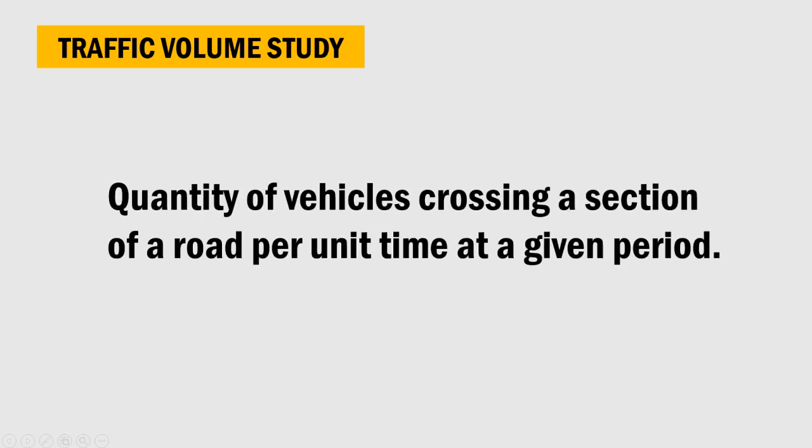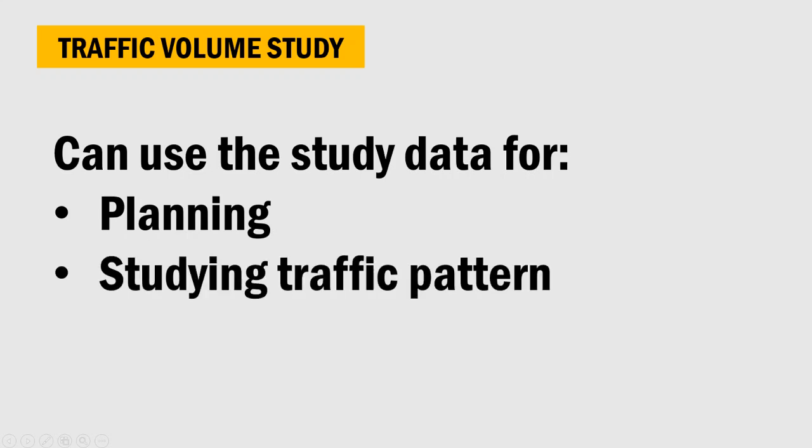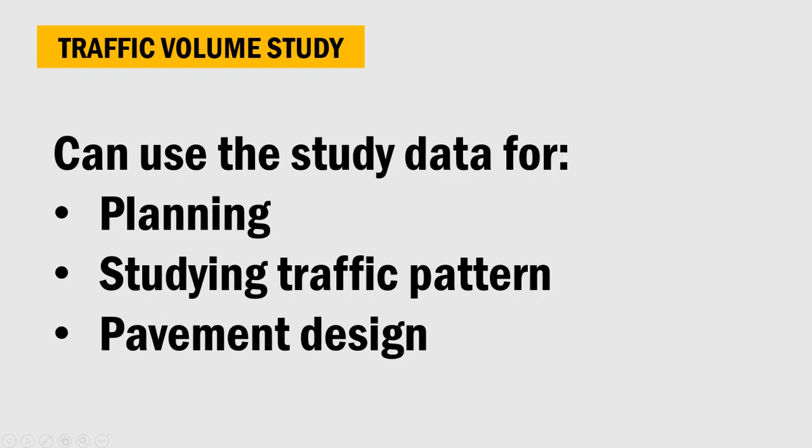Now let's talk about traffic volume study. The quantity of vehicles crossing a section of a road per unit time at a given period, we define as traffic volume study. The data collected from traffic volume study can be used for planning, for studying traffic patterns, and pavement design, as a roadway with higher volume requires stronger pavements.